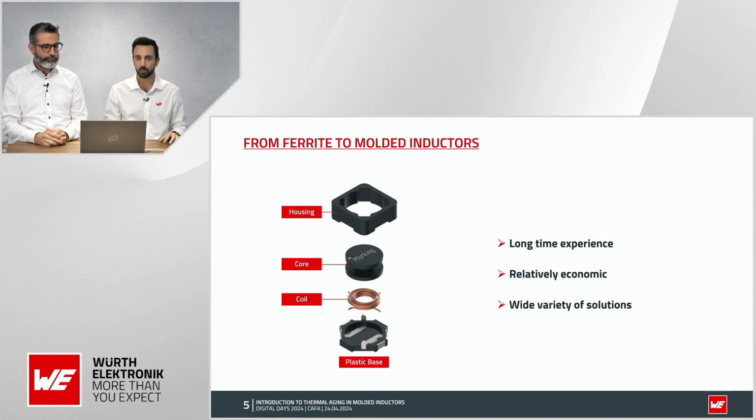Ferrites are a very nice option because they have a very high permeability, so they allow us to build inductors with high inductance, a low number of turns, and low RDC. They have good saturation behavior, and a very high volume resistivity, which we will see later is very important regarding the core losses. They have also been available in the market for a very long time, and we have accumulated a lot of experience with them.